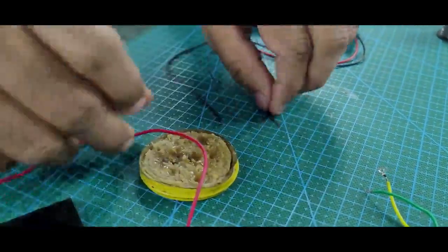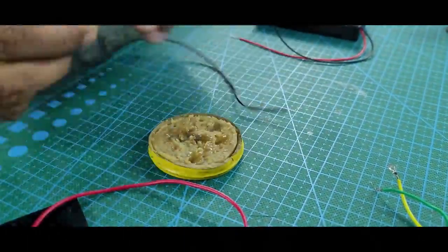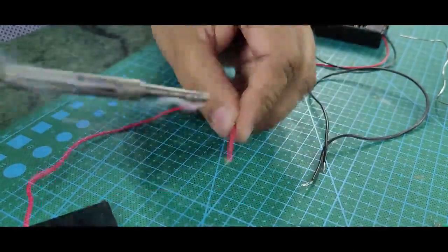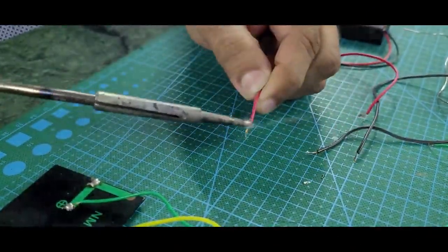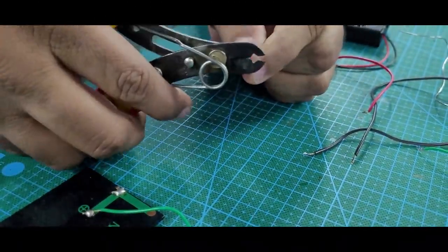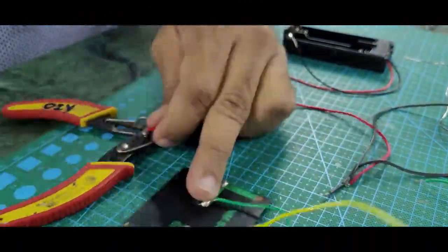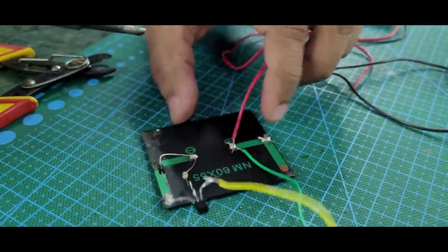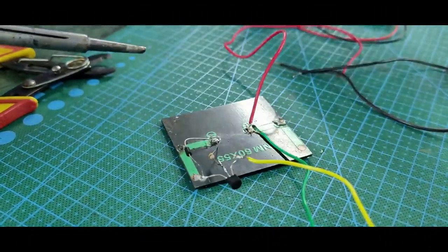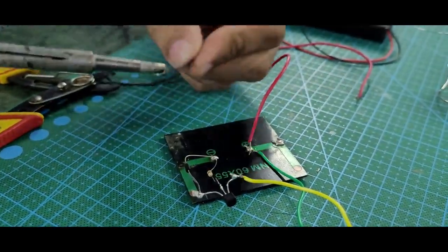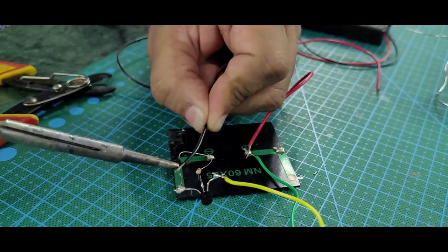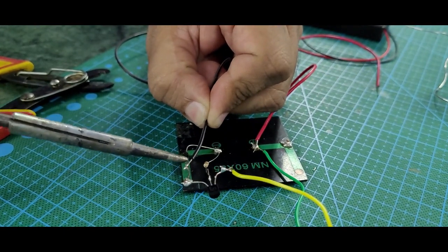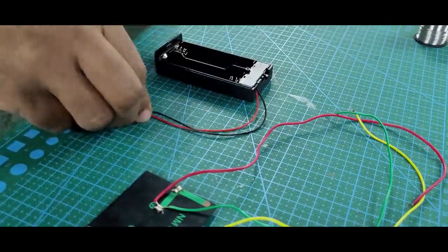So same process. Why it is important to apply the metal onto the cables is because it is easy to solder them later. So we have applied metal on both the ends of both of these wires. Now what we are going to do is connect the red wire to the positive terminal of the solar panel along with that green wire, and connect the black wire above the diode, that is on the opposite side of that white line, or you can say towards the transistor end. Do not connect it onto the white line.